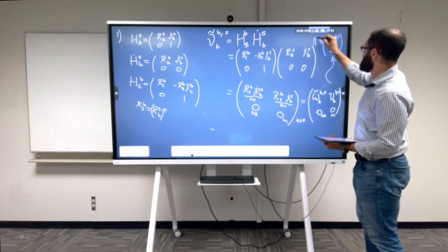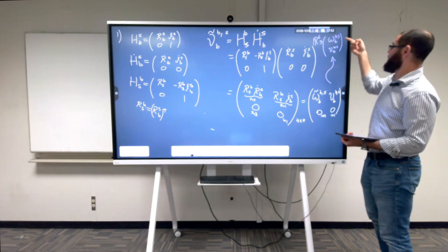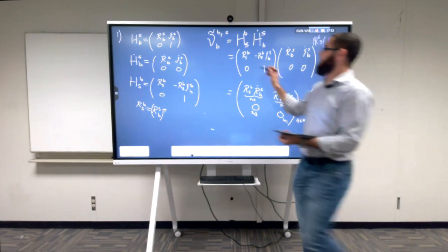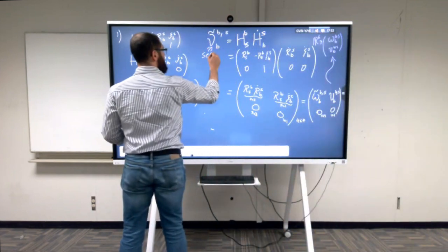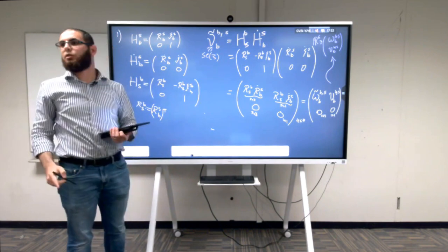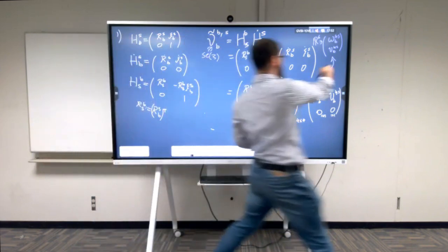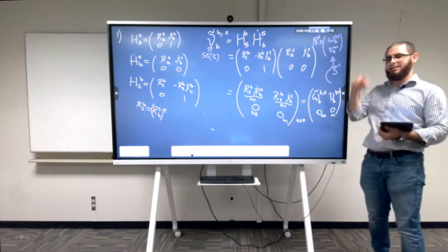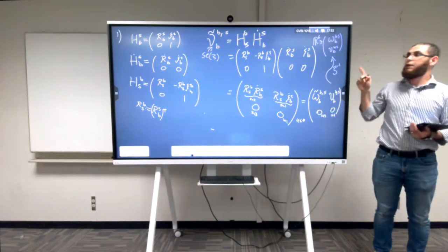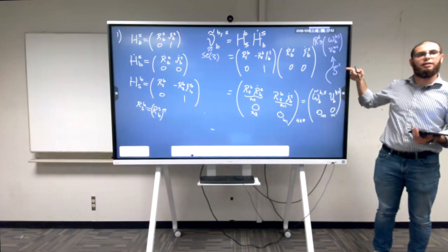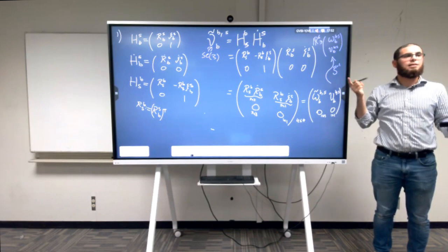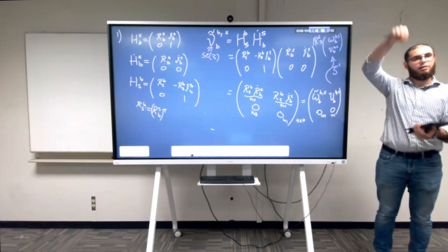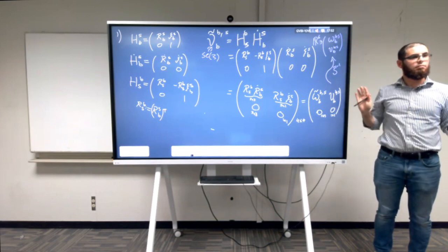And what's the dimension of this? It's in R6, because the first one is 3-dimensional, the second one is 3-dimensional. But this is a 4x4 matrix. In other words, this lives in small se3, because this is an element of the algebra. And this is its corresponding isomorphism. We're going to be calling this isomorphism S tilde inverse. This is just a name for it. If you go from this guy to this guy, we call it S tilde. You go from that guy to that guy, we call it S tilde inverse. It's just a name for taking all of these elements and putting them in a vector form. Easy? That's it.